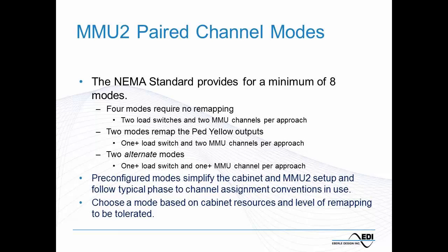Part of what this webinar is going to assume is we have a 16-position back panel. We're in TS2 mode. We're not really going to discuss NEMA TS-1 12-channel mode, although it is supported by some of these modes. If we don't have enough load switches and/or channels, we have to start getting clever.